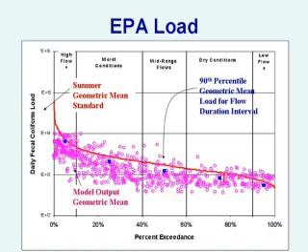That regression equation shown by the pink line is about 10 times the average of the CSOs. And even then, in Columbus, that shows we've gone from 3% excursions to about 6% excursion rate. It's well below the 10% that's allowed in their impaired water listing protocol. And the state of Georgia is actually looking at adding the frequency of excursion to their natural variability clause in their water quality standards. This plot shows an EPA method of looking at the loads over a range of flows.